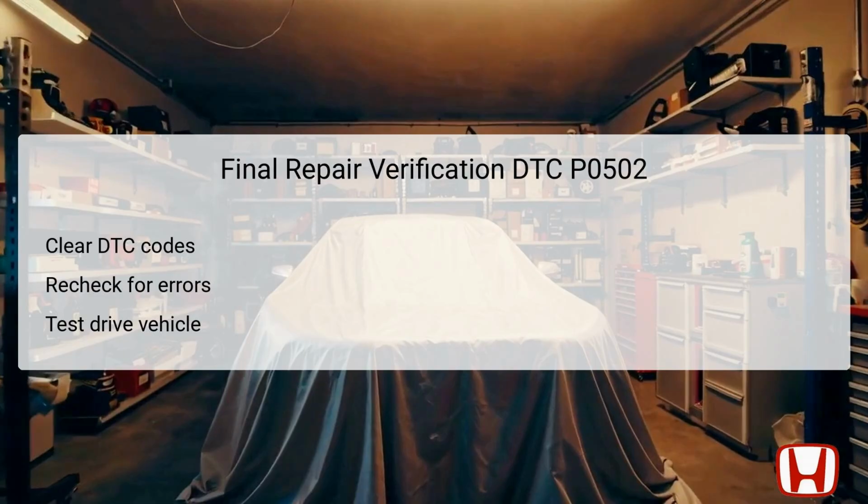After completing the necessary repairs and component replacements, it's essential to conduct a final verification to ensure that the DTC P0502 has been resolved effectively. This involves first clearing any diagnostic trouble codes, DTCs, stored in the system, allowing the onboard computer to reset. Following this, a recheck should be performed to ensure that no new error codes reappear in the system.